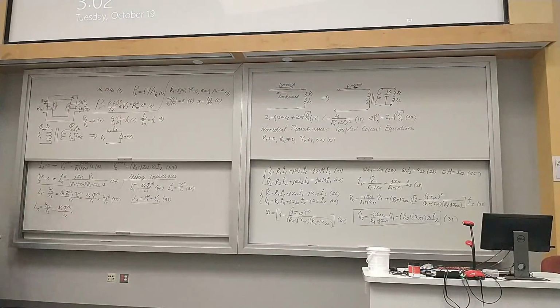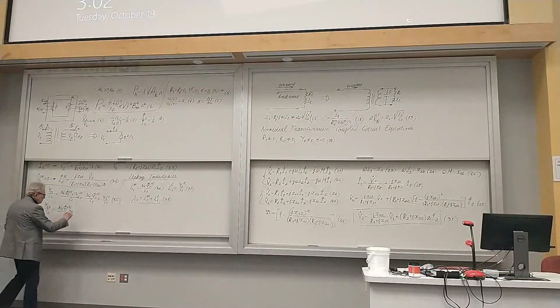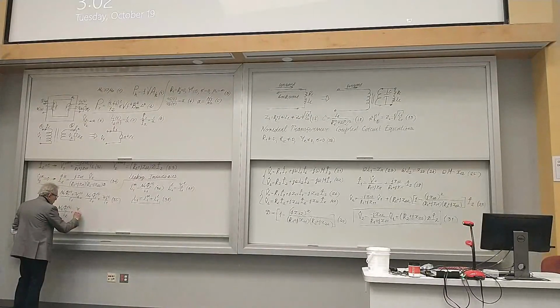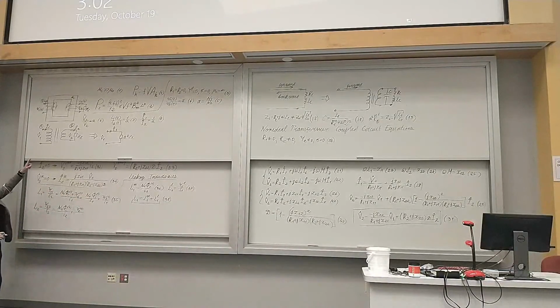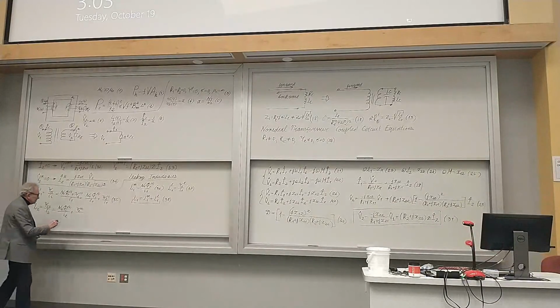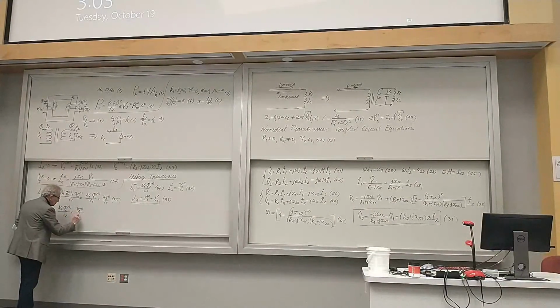And this flux will link all turns of the secondary winding because all of them are confined to the ferromagnetic core. And then there will be an additional term, due to the magnetic field lines which partially leak out and link the turns of the secondary winding, divided by I sub 2.